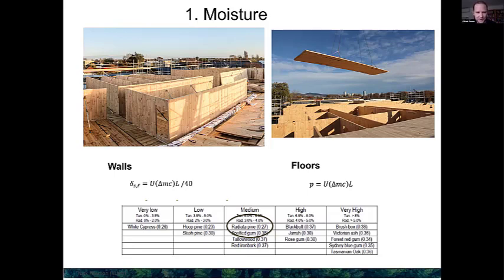And the value is going to be different for floors and for walls. If you think about how a tree evolves, it evolves with all the grains going in one direction, and it's designed to really take moisture from the top of the tree down through to the tree trunks. So when you get the moisture going through the parallel grain, in the direction of our walls, there is much less movement than there is for floors. Floors have about 40 times as much movement per unit length.